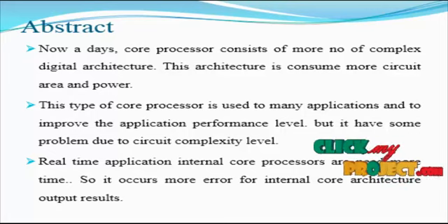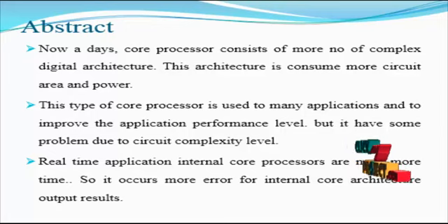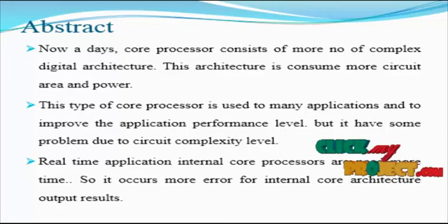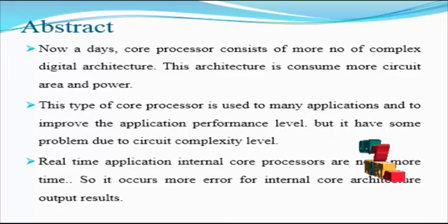The most common technique is triple modular redundancy, a particular case of N-modular redundancy. Quadded logic is a fault-tolerant technique in which a quadded number of gates are connected in a systematic manner such that the alternating layers of logic correct a single error in one of two layers.